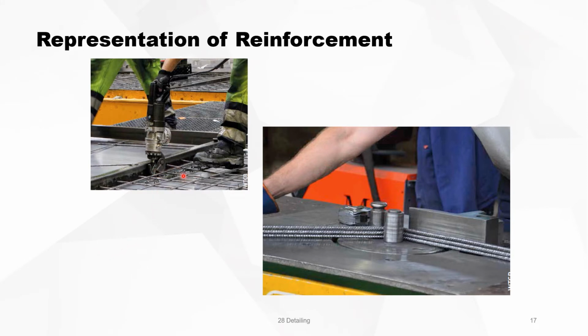This is a typical cutting tool where you cut the rebar. This is when you do the bending on site, not in a factory, but when you do the bending on site, this is a tool to bend rebars. And you can appreciate now that if you have bends always in the same direction, it's much easier to use this tool. Also use bends always in the same plane. Don't use bends in different planes because you cannot do it on site.